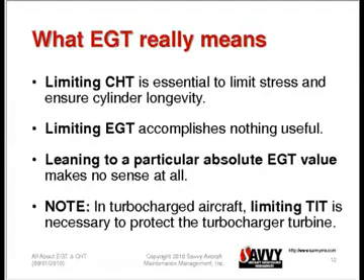Similarly, if the mag timing is retarded, if it's misadjusted and the spark plug is firing too late, EGT will rise. Does that mean that the engine is under greater stress? No, it's under less stress. When we have retarded timing, CHTs go down, EGTs go up. The engine produces less power than it's supposed to, and we see that in the form of increased EGT.